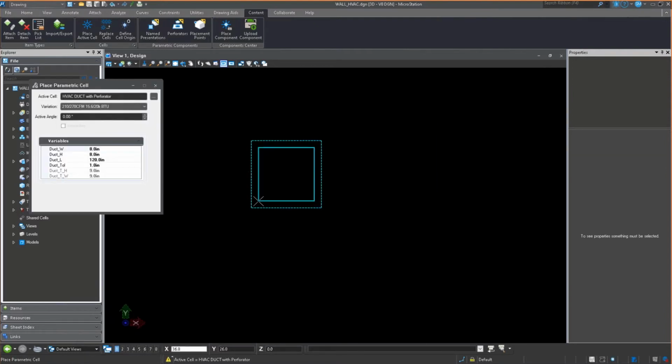You'll notice that you see two cyan lines, right? The inner line is where an HVAC duct would be, a metal duct. The other line that's there, there's a collar or tolerance, a distance around it, that would be where we're cutting an area through the wall to place the duct into. So we're going to cut it a little bit larger. Now mine's exaggerated, but just so you can see, you've got an area that you would cut and then the duct would fit inside that.